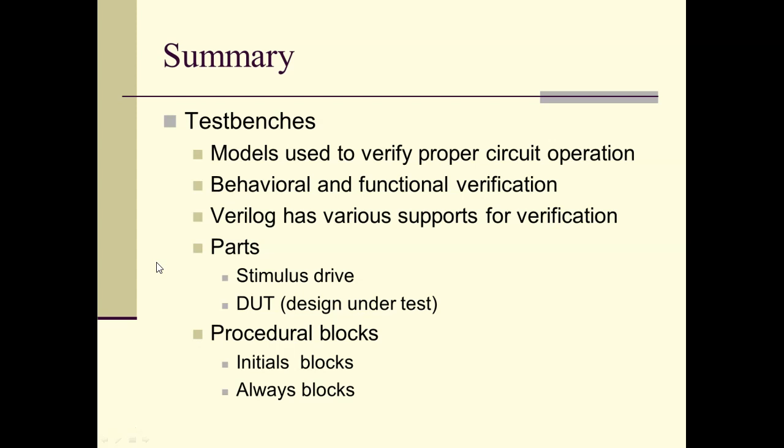The two parts of a test bench are the stimulus driver and the design under test. The stimulus driver is essentially a Verilog model full of stuff that's not necessarily synthesizable. We learned about initial blocks in this chapter, which is a procedural block that executes once at time 0 in your simulation. It has some similarities with an always block, but is a little bit different in general.